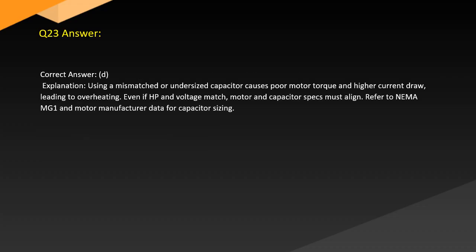Answer. Correct answer: D. Explanation. Using a mismatched or undersized capacitor causes poor motor torque and higher current draw, leading to overheating. Even if HP and voltage match, motor and capacitor specs must align. Refer to NEMA MG1 and motor manufacturer data for capacitor sizing.